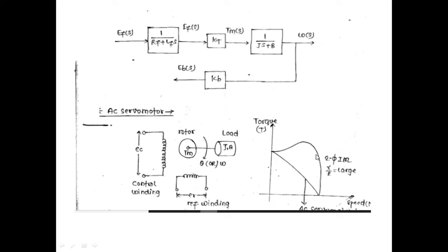So obviously, automatically, the speed of the motor may have increased, and the reduction in the torque, which was due to the load, was being compensated by the characteristic of this induction motor, by the slope of the characteristic curve, which has resulted in the fact that at a reduced speed you have obtained a larger torque, so there was an equilibrium again.